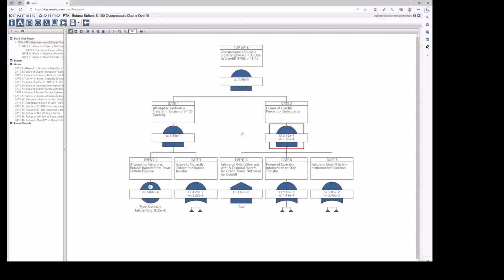Okay, yes, that does answer it. There's a question here. Does this also show shared IE and alarm DCS? So if you think about this in LOPA, this here is telling me my initiating event. Then I have 3 protection layers. One is the relief valve that I didn't take credit for. One is operator intervention. One is the safety instrumented function.